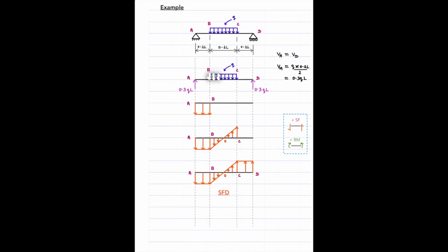As this force is acting downwards, which is also varying uniformly, then the shear force diagram should have a variation like this. Why? Only then, if you find the slope, it's a constant slope, and its negative value is equal to the intensity of the UDL applied here, which is also constant, right? So this variation should be like this. That's what happens for this span BC alone, right? So we start like this, then for span BC it should go like this, right?